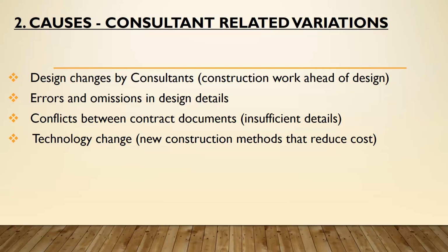And the reinforcement size specified in the design was 12 millimeter instead of 32 millimeters diameter. So this was a big error, and once the contractor realized it, he notified the consultant, and the change was effected, and this brought about a huge variation.